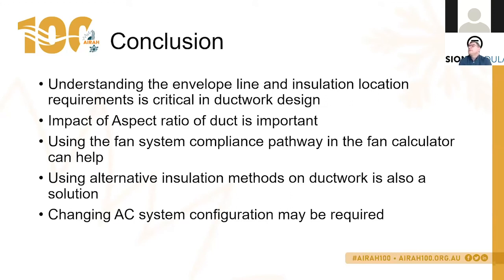The duct within the building envelope can still run into an unconditioned space, which could be pretty hot. It would not make sense to reduce the duct insulation. No, it wouldn't. And yes, ductwork that goes from a conditioned space into a non-conditioned space does then need to be insulated in accordance with the requirements. So that non-conditioned space could be pretty hot.